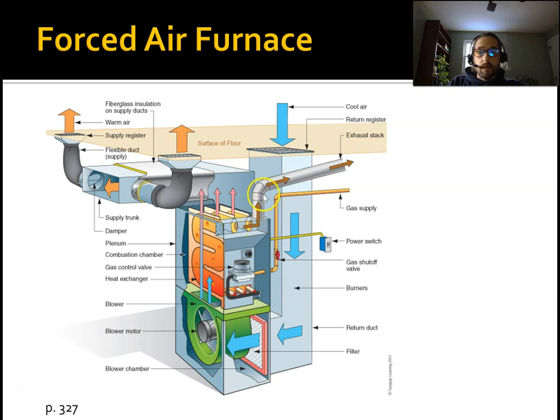And then, of course, you don't want any of those gases in the house because there's carbon monoxide, there's carbon dioxide, there are particulates. You don't want to be breathing that in. So this heat exchanger has to be totally disconnected in terms of airflow from the forced air part. You have hot gases going through here that are then blowing out the flue. If you have a crack in your heat exchanger, for example, that's dangerous, and you have to replace the heat exchanger or just replace the whole furnace. And that's the basic process here.